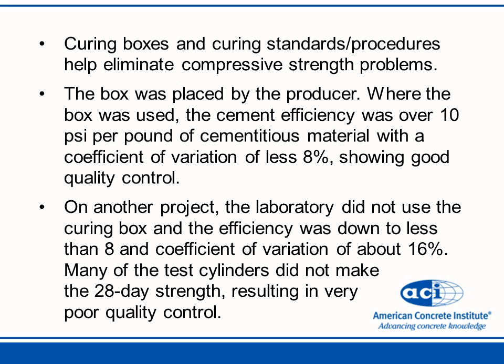And also many of the cylinders did not make the 28-day strength, resulting in very bad quality control. So if the cylinders are not properly cured during the first 20 to 24 hours or over the weekend, you're going to have a lot of problems.